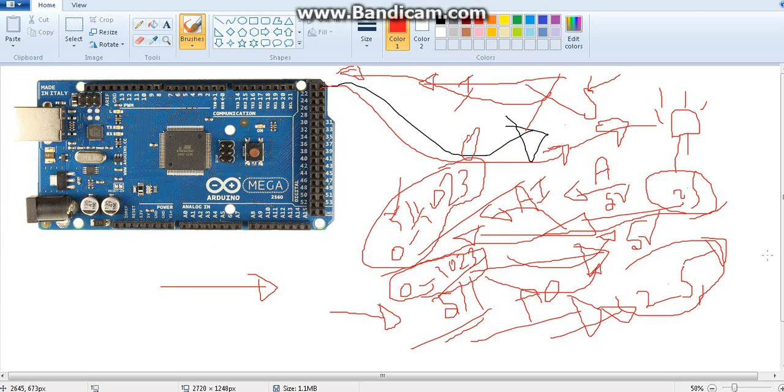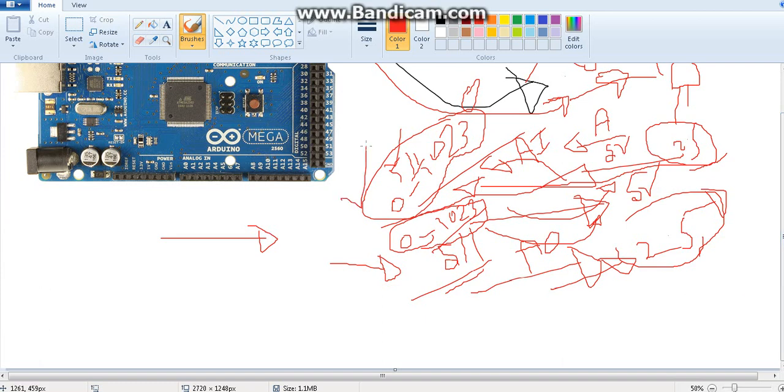I want to just remind you, give a hint. When it is coming as input, we know it is 1024 units, right? We are dividing the 5 voltage into 1024 units and reading the particular number. But when we are giving an output, we are not capable of giving 1024 units. We are giving only 256 units. So the minimum value is 0 and the maximum will be 255. You understand what I'm telling? Because maximum is the total number of units minus 1, right? We have seen those things in the analog input part. You can watch those videos if you don't understand.